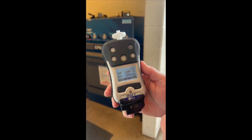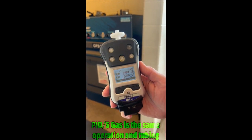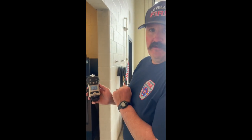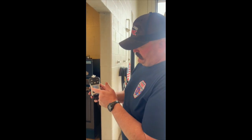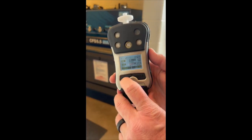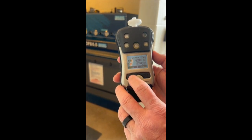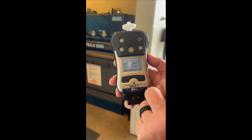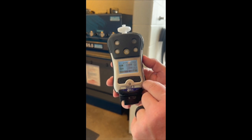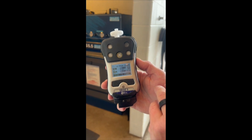So if we use the method where we were not able to attach tubing and we had to lower the monitor, or if we wanted to come back later and see what our maximum levels were or our minimum levels, then with this CGI from this screen, if we hit the arrow button, the button below the arrow, it will scroll through our different values. And these are cleared every time the monitor is turned off and then back on. If you wanted to clear those values, you could do that by hitting the button here under clear. But in this case, we don't want to clear it. We want to log the information for the entire incident.